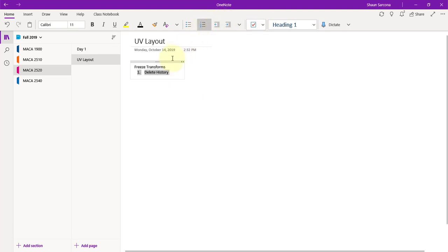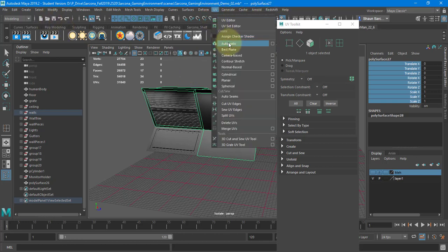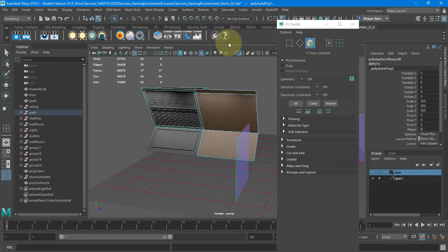And if I go here and say this, oh, come on. And now we have actual numbers. Hooray. All right, so we deleted history. We froze the transforms. And then I'm going to go under UV, and I'm just going to say automatic. Okay? And this is the easiest way to get started on a surface like this.